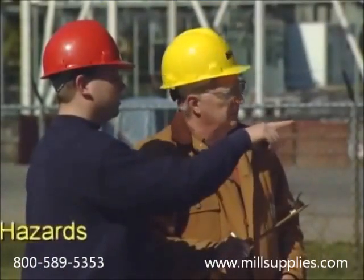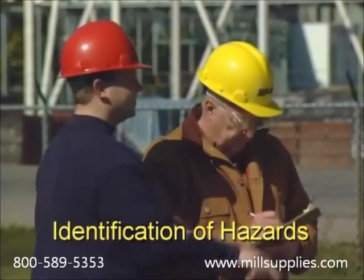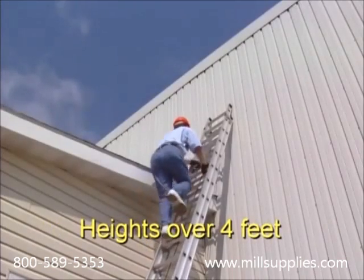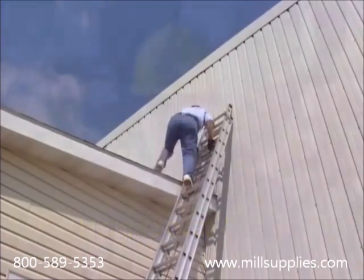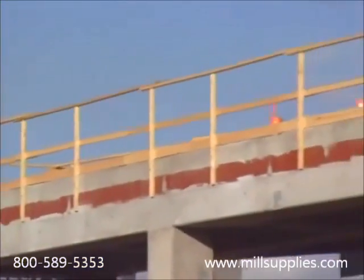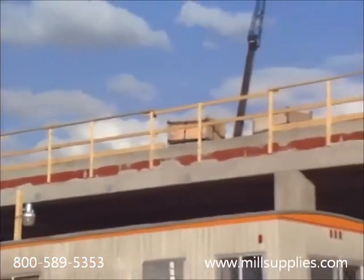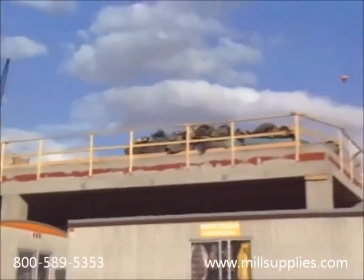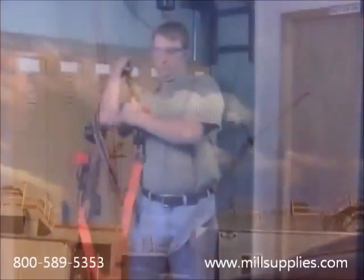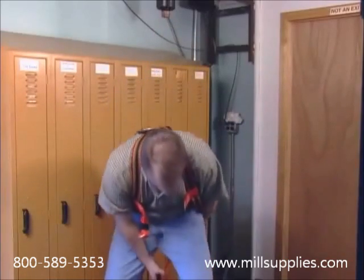A well-conceived fall protection program begins with the identification of all fall hazards in the workplace. As a general rule, anytime a worker is at a height of more than 4 feet, a fall hazard exists. When a hazard is found, 2 options are acceptable. First, the hazard can be prevented by eliminating it. Prevention methods can include engineering solutions such as guardrails or simply avoidance of the hazard. This is the ideal approach, although it may be impractical. Second, protection can be provided through the use of personal fall arrest systems.